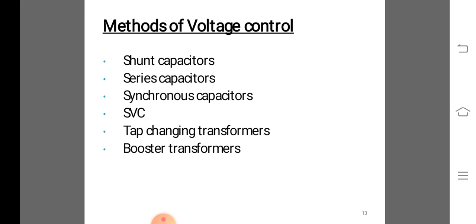Regarding the relative merits of shunt and series capacitors, if the load VAR requirement is small, series capacitors are of little help. Then, if the voltage drop is the limiting factor, series capacitors are effective. Also, to some extent, the voltage fluctuation can be evened out.